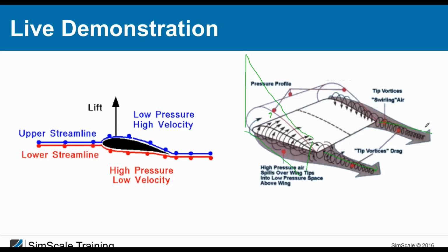And these vortices, let's say it in a very unscientific way, are destroying our energy. They are transferring the kinetic energy of the airstream into rotational energy. We have a high pressure drop, and this will create additional drag and for sure also reduce the lift.